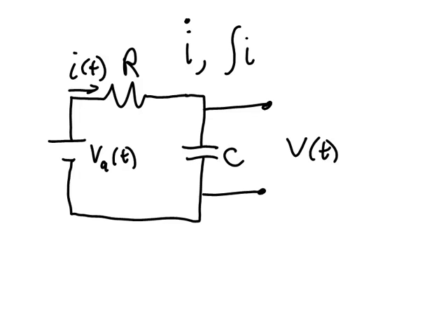When we're doing a modeling operation using the Laplace transform, trying to find a transfer function, we always have to get rid of these signals that are not the input or the output. In state space modeling, we don't necessarily have to get rid of these signals that are in between the input and the output. These signals can be our states. By allowing us to have states in the equations that we come up with, that can simplify our task of coming up with a system model.